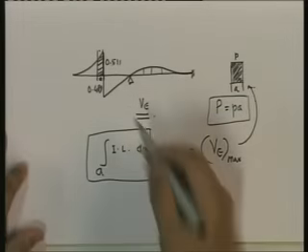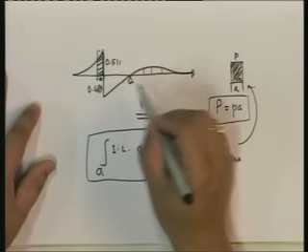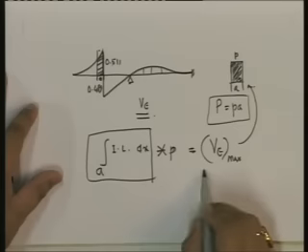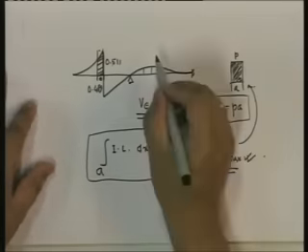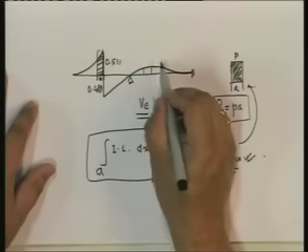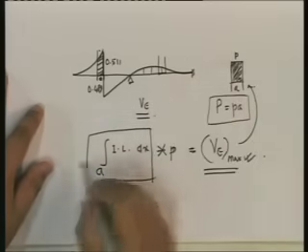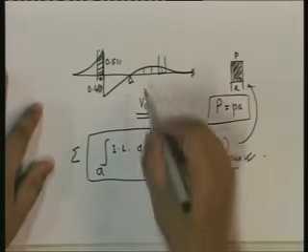How do we integrate? We actually don't integrate it analytically. We discretize it and then numerically integrate it, and you've got your VE max. Of course, once you place one load, the other load may come here. All you need to do is sum up the influence lines.